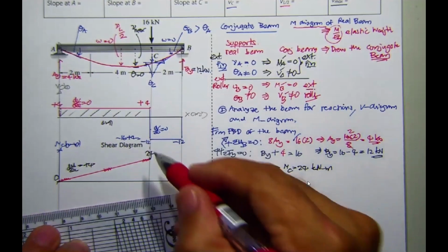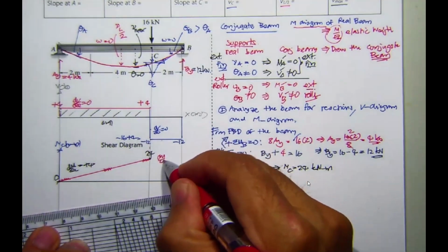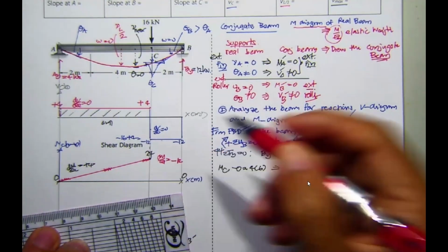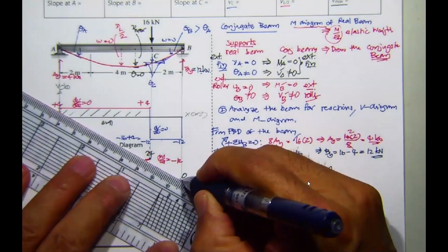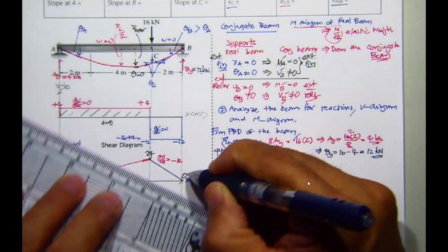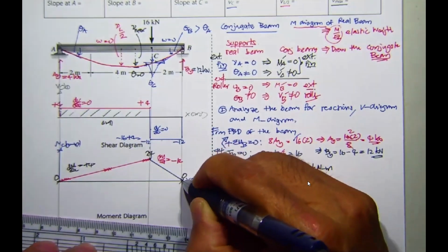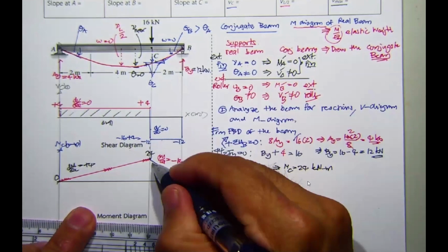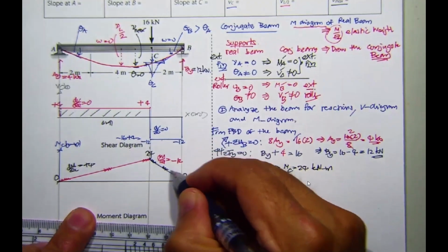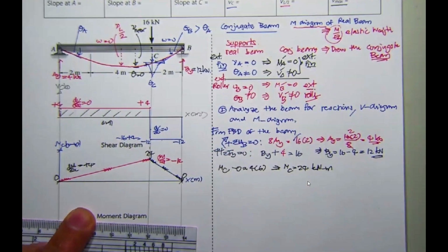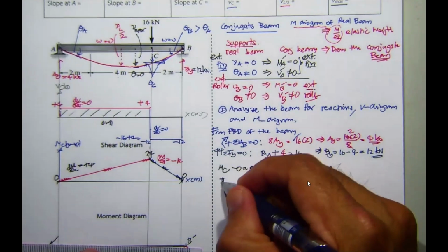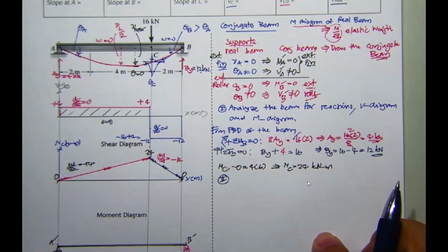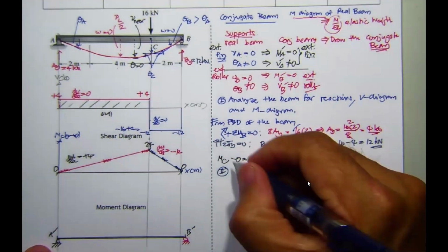Then moving this one, dm by dx is going to be minus 12, and for sure you just draw the line link between them, because this is 0 due to the roller over here, and you understand the slope is going to be something like this. Now you are ready for what? For the second step.